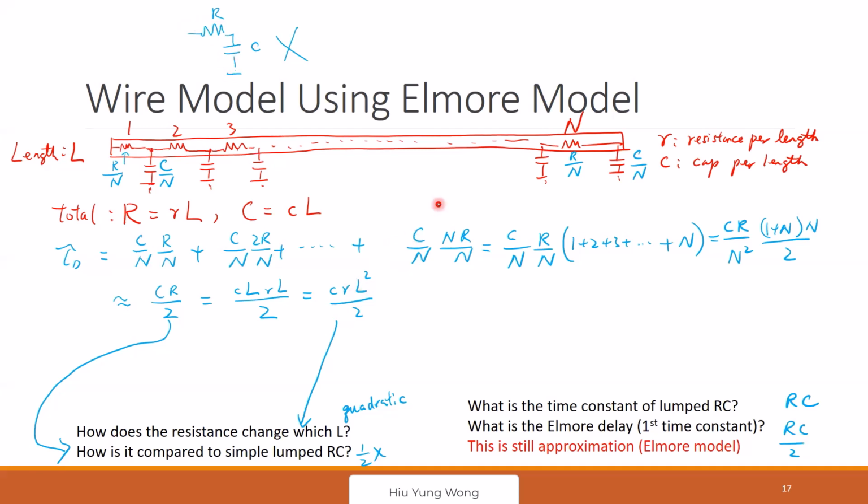So you're paying a lot if you are lazy and try to say, let me just connect this wire to that gate. Then maybe that is not a good idea. The computer can simulate for you, but this type of insight is very important when you design, because the computer can never find the global optimum, in my opinion. So you need to start with something good instead of asking a Synopsys or Cadence tool to optimize for you. They will, but they cannot get you out of some very bad local optimum. Okay. Any questions?